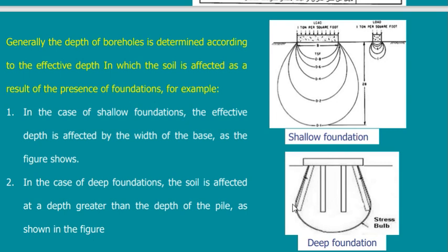Your experience will tell you that in a building that is expected to have, say, 4 floors, I expect my foundations to be of a maximum width of say 3 meters. So 3 meters by 2, it's 6 meters. So if I take 10 meters, it will be fine with me. Also for piles, in a building of 10 stories, I expect that my piles will be so and so, and I put that.